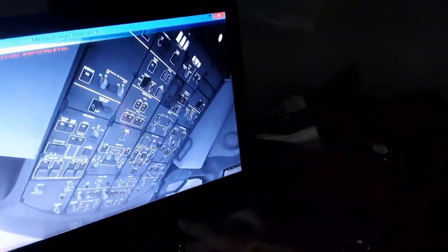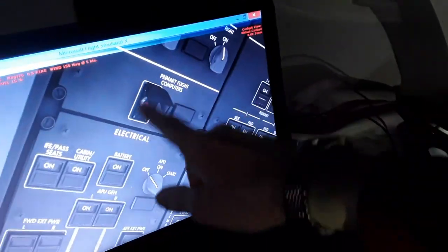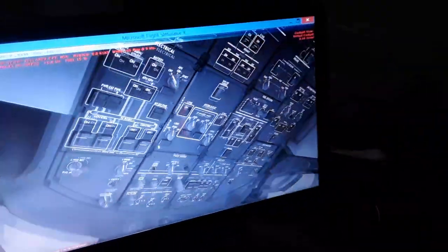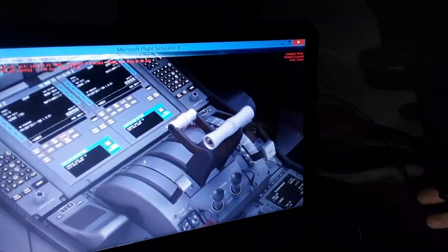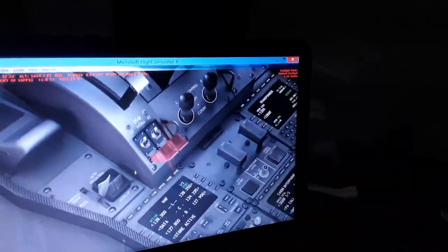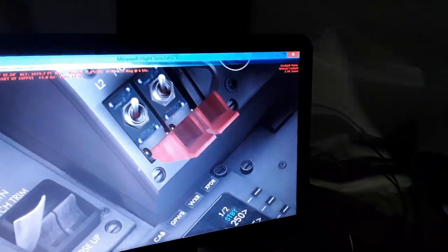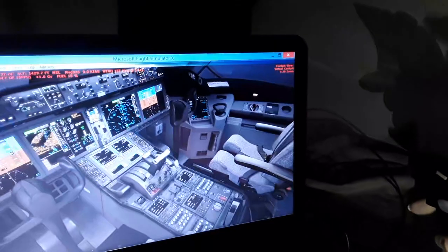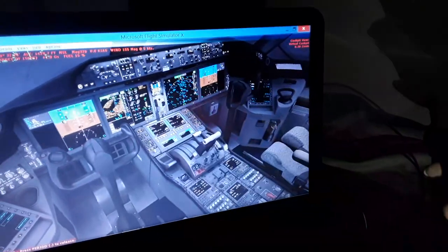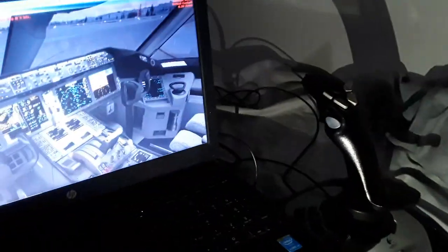So it has the flight control computers, and as I told you, if we have a degradation from the hydraulic failure, we need to disconnect the horizontal trim stabilizer over here, and we're going to lose the auto trim function. So use only the manual trim switch after. So this is most of the flight controls.